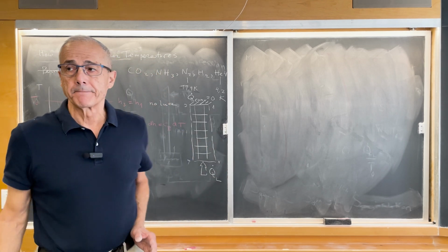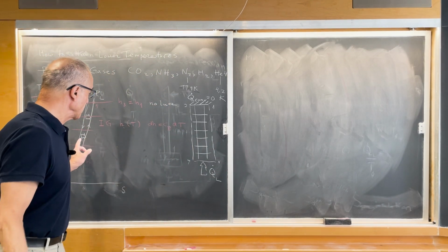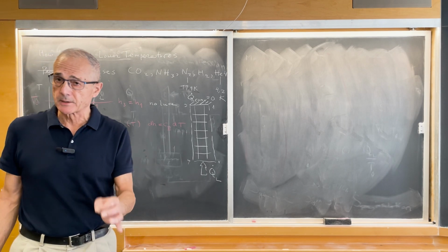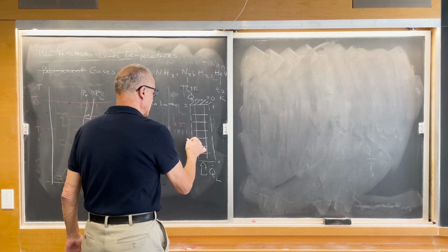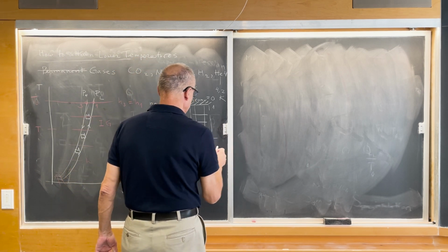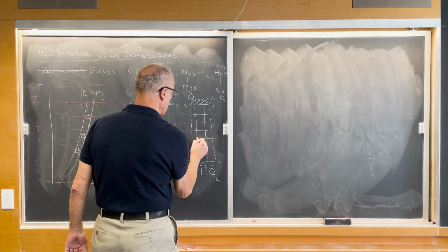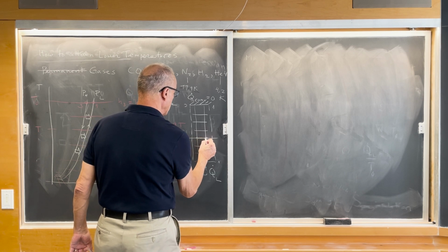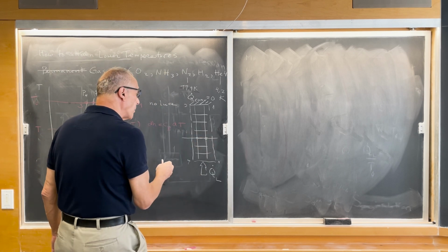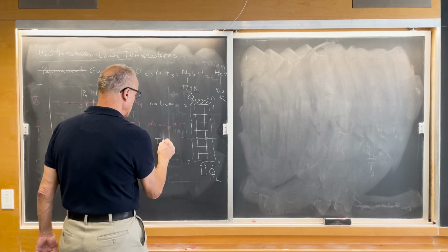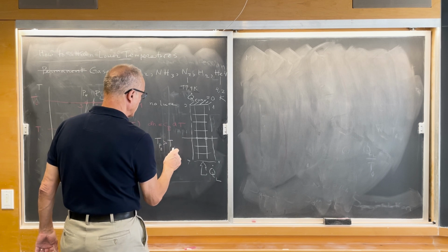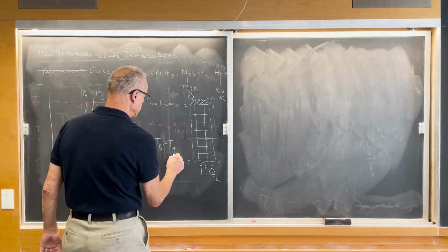and for the stream-to-stream heat transfer to take place, it is necessary at every location for the temperature of the high pressure stream to be higher than the temperature of the low pressure stream.